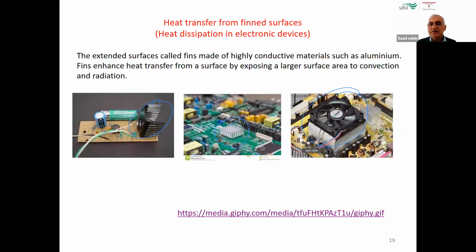We have the fins component or fins block, and on top of the block there is a fan. This will improve the heat transfer even more, because we have more area and also more flow of air through the area. So we are actually improving the heat transfer from this component.